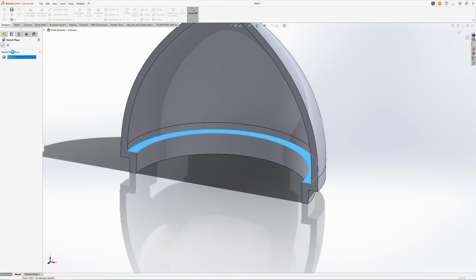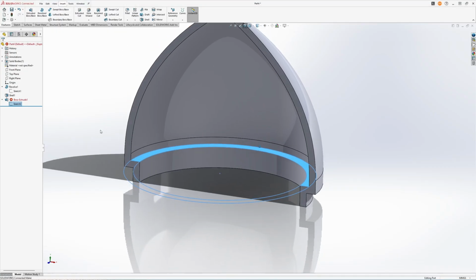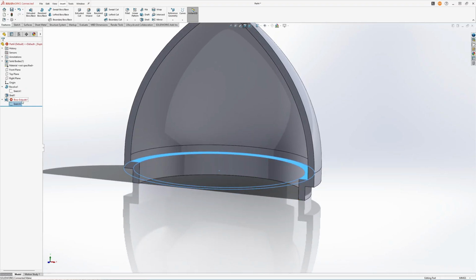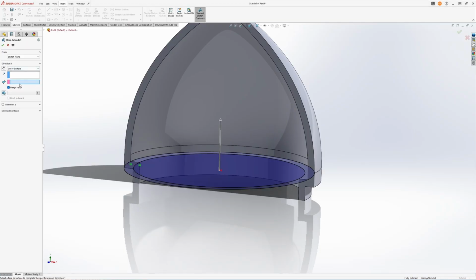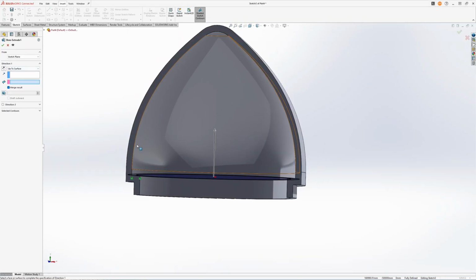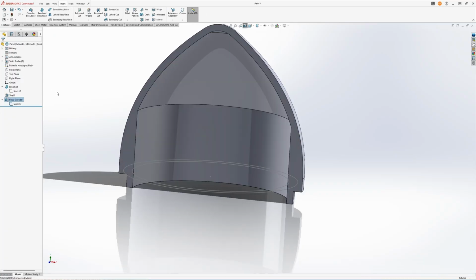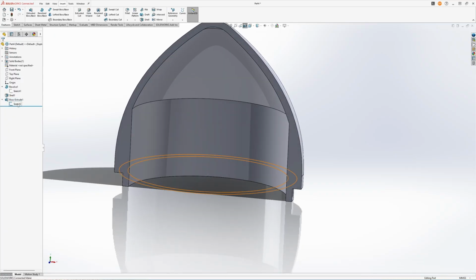That was not the issue. So the issue was it knows where to start. It knows this plane, but it can't find out where it should extrude to. So let's go back in here. And that's that face there. And it makes sense because that was what we changed just now. We changed this geometry. So we just click, that's the face we mean. And now it's happy again.